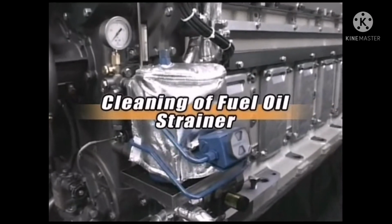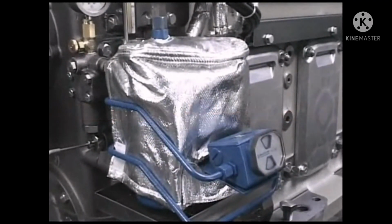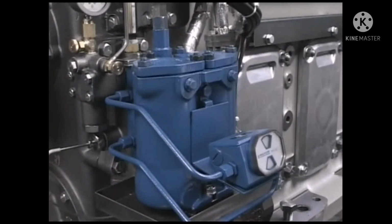Next, I will explain how to disassemble and clean the fuel oil strainer. There are two units of the same fuel oil strainers on the right and left side respectively, and they are used with the fuel oil filtering elements on both sides during the engine operation. When you disassemble and clean them during the engine operation, conduct the work one by one according to the following procedure.